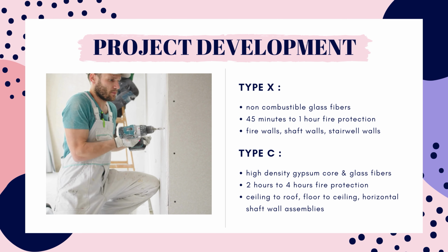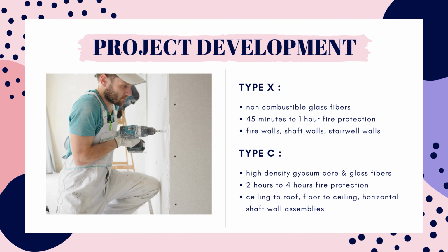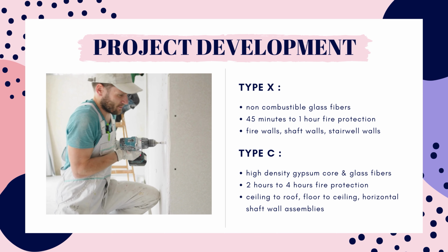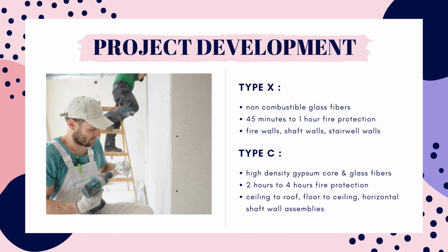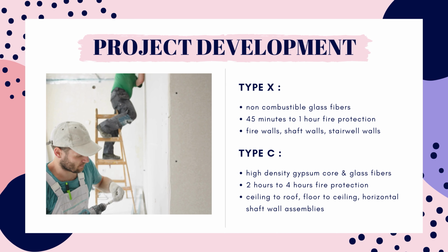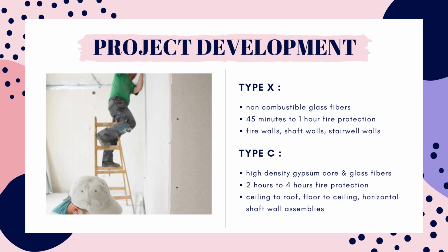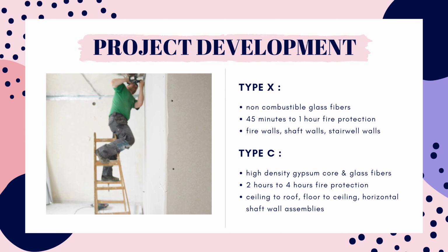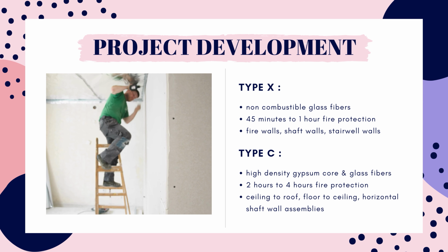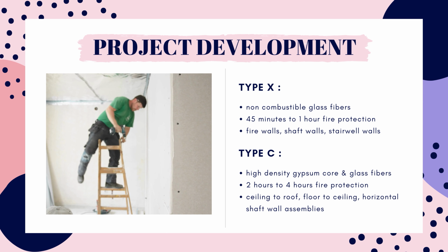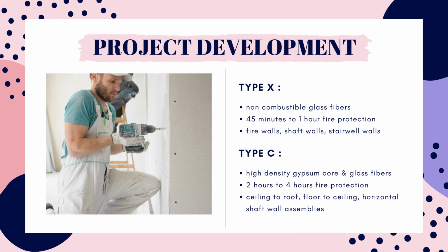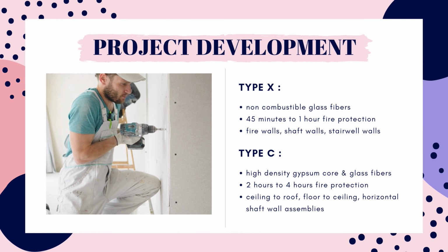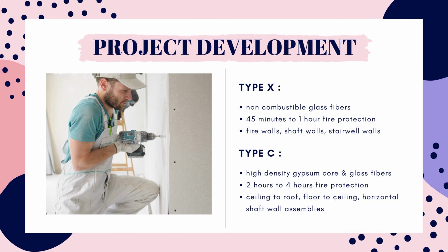There's really no industry-defined special fire-resistant board beyond Type X, since it meets the minimum requirements by ASTM C1396. While enhanced panels like Type C have been evaluated and approved to be used in more challenging constructions due to their superior fire-resistant qualities, these panels are technically still Type X by definition, since they meet the minimum requirements of ASTM.